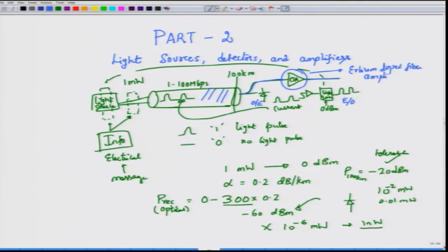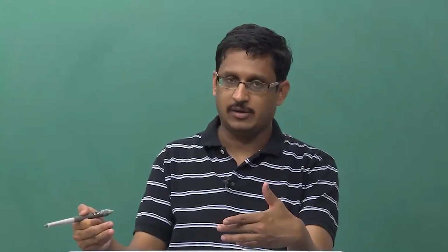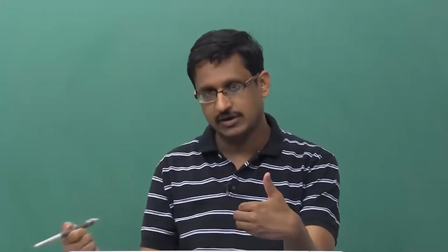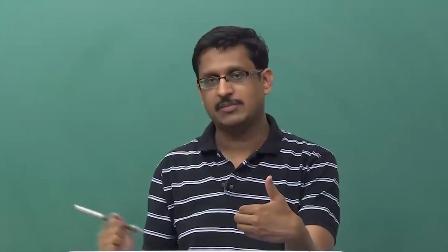And this was a fiber amplifier in the sense that the optical amplifier was not a device wherein you had to take light from a fiber, amplify it and then convert back into the fiber, because you could have significant losses in taking light from a fiber, processing it and then focusing back into the fiber. So, fiber to free space conversion is also avoided because these early optical amplifiers were actually fiber based amplifiers.